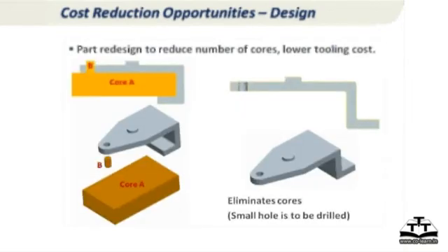Okay. And some more examples from the ASM book now, and 3D. The ASM book is 2D, here it is 3D. You see core, if you have a step like that, undercut there, you may need either 1 core or 2 cores depending on how you want to make that. But if you just make the step, remove the undercut there, you can make it without any cores at all. 0 cores here. 1 core or 2 cores to 0 cores is a big improvement.